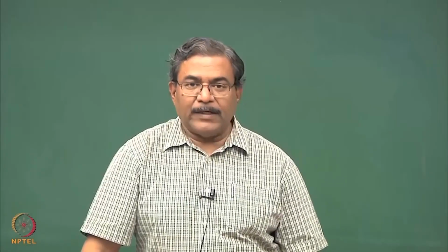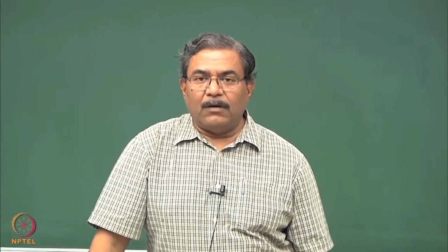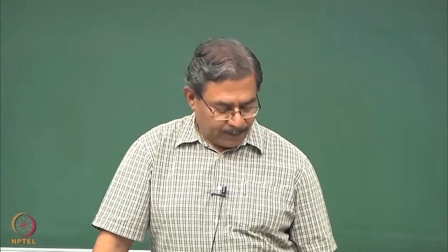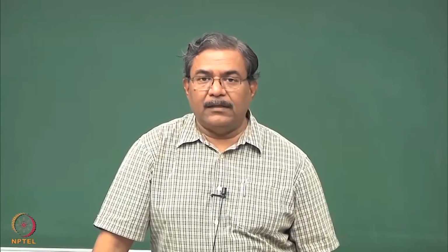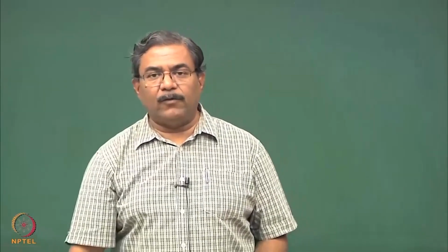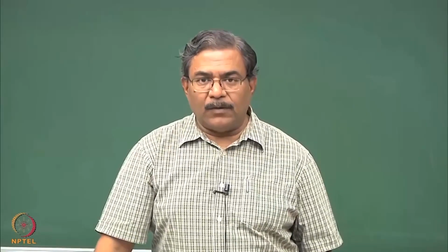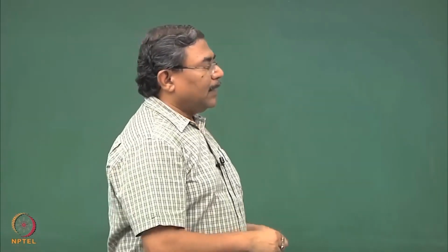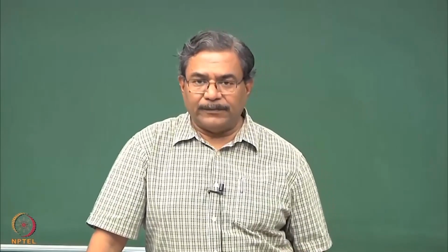Welcome to lecture number 23. What we have realized is that once you solve the one dimensional consolidation equation proposed by Terzaghi, the coefficient Cv, which we have defined as the coefficient of consolidation, remains unknown, and hence we have to conduct experiments to obtain its value.